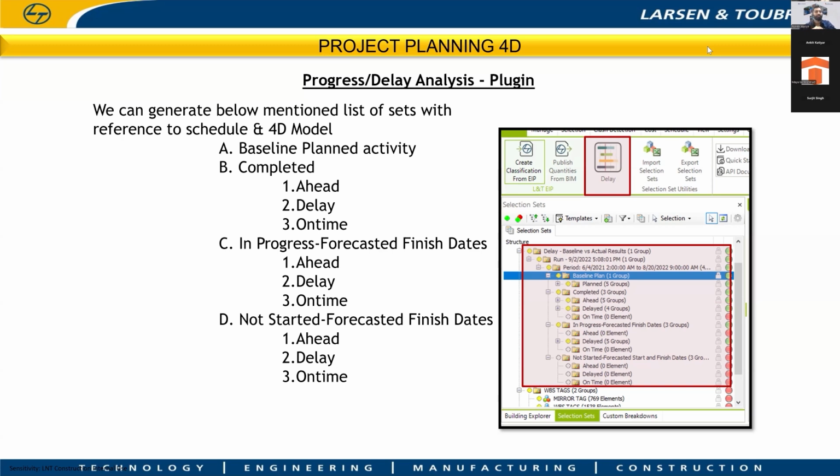It depends on the project, but we have a facility where you can update your actual schedule in real time. We have a cloud platform where you can take the model to site and update the daily progress through BIM, and that information you can bring back to your integrated platform. So it's a project call whether they want to track the activity on a daily basis or over any time period. That is also possible.